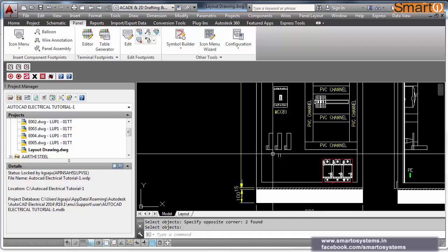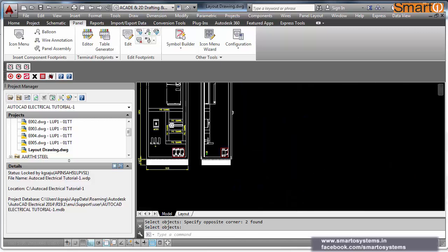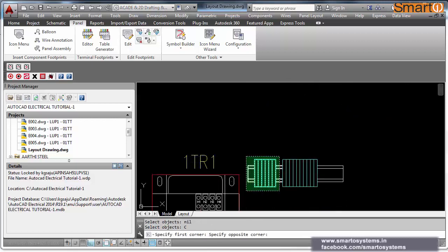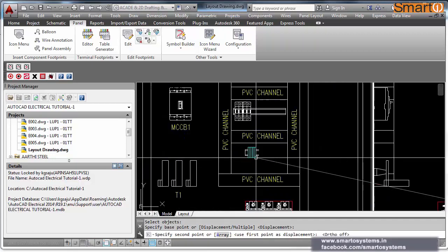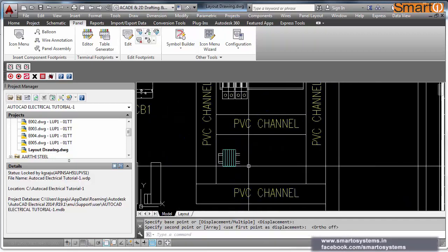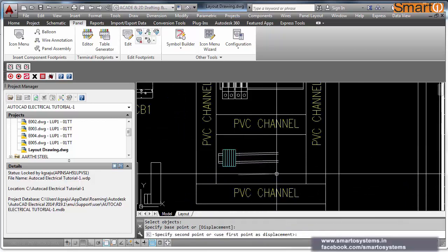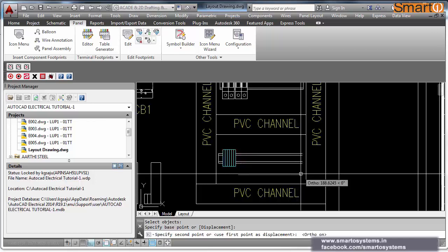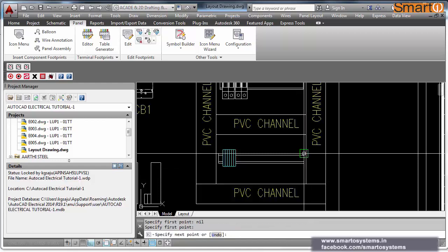And of course you can do the dimensioning, especially for major things like the distance between the bottom and the termination. Many customers will ask you to give a clearance of 250-300 mm minimum for power cables, and if it is control terminal blocks, you can adjust a little bit. If I want to keep some control TBs here, everything should be in one sheet so that you don't have to look for the blocks.